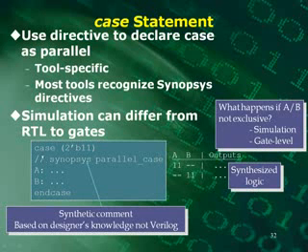You put your comment line, then synopsys, and then some information after it, like in this case parallel case. So we're telling it, if you're using the Synopsys tools, that these are going to be mutually exclusive. I want you to generate your logic as though these two things are mutually exclusive. Okay, and then it would actually produce mutually exclusive type code.